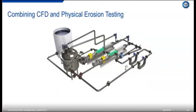Now CFD is obviously a very powerful tool, but it's not infallible, especially when it comes to erosion testing. It's very good at determining areas of erosion and hotspots of erosion, but when dealing with the exact magnitude of the erosion, it can be slightly off, especially if it's an exotic or a new type of material. But one way you can improve the performance of CFD models is to combine it with a physical test.